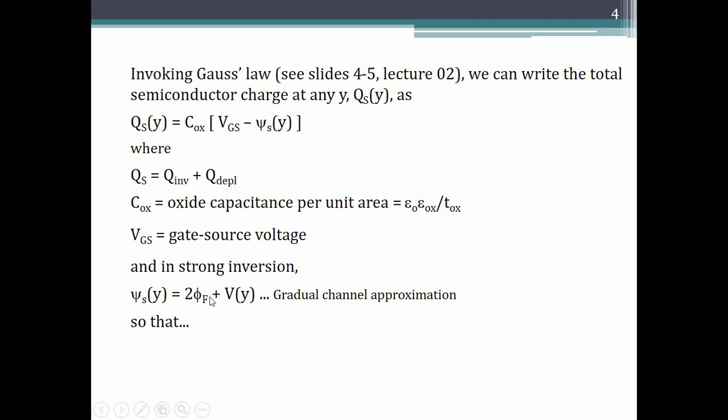If you actually want to find the electrostatic potential at the surface of the semiconductor, you have to solve a two-dimensional Poisson's equation. It is very messy, it is very complicated, it actually cannot be solved. So this is an approximation that has been used for like 70 years, I think, maybe 65 years. Alright, so this is the equation we'll use.